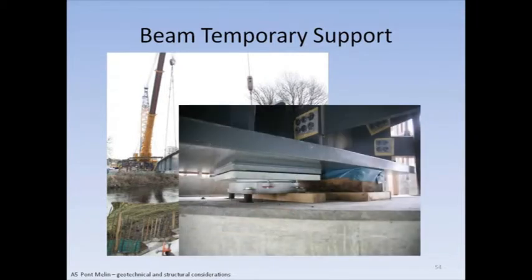You can see it just at the back of the beam there, the blue visqueen, and the final bearing was in place on the bottom of the beam, but it wasn't grouted up. It was just held in position while settlement went on. And it proved to be an acceptable way. There was always provision to lift that up had there been the need, but the contractor went for the hardwood block, and it worked.